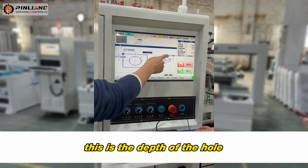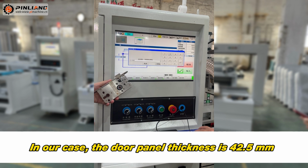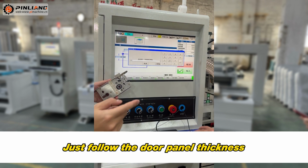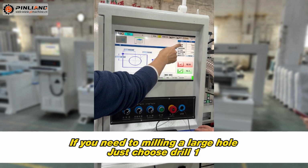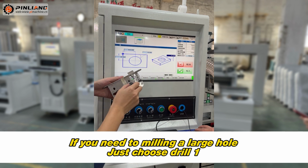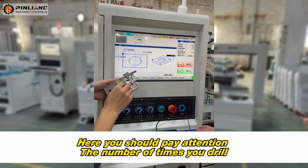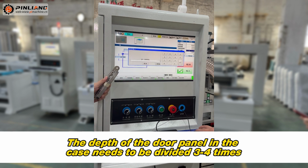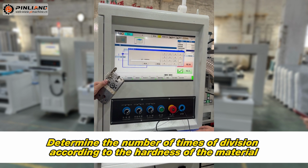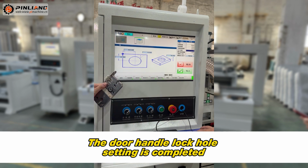This is the depth of the hole. In our case, the door panel thickness is 42.5 mm. Just follow the door panel thickness, then pay attention to the drill number here. If you need to mill in a large hole, just choose drill 1. Here you should pay attention to the number of times you drill. Because you can't drill too deep, the depth of the door panel in the case needs to be divided 3 to 4 times. Determine the number of times of division according to the hardness of the material. The door handle lock hole setting is completed.